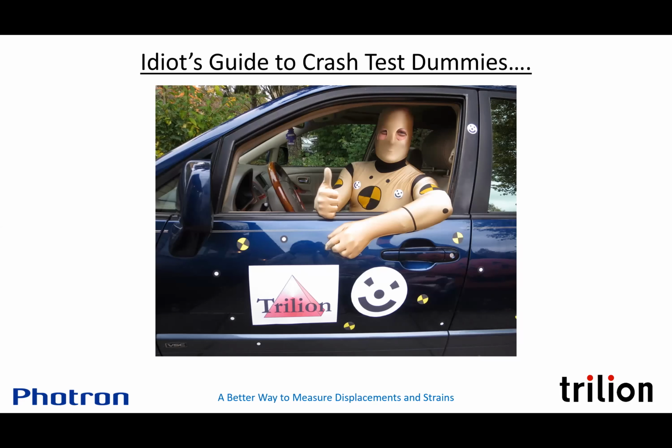Right. Okay, that's a great question. And again, sorry, in this seminar we skipped over some of the little bit deeper details on how DIC and stereo pairs work. We have calibration objects ranging in size from 10 millimeters up to 2 meters, and that can be used for up to 5 meter field of view. Basically, you take a sequence of pictures with the stereo pair of a known dot pattern at different distances and tilt angles to the cameras.